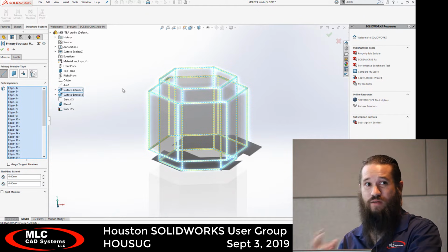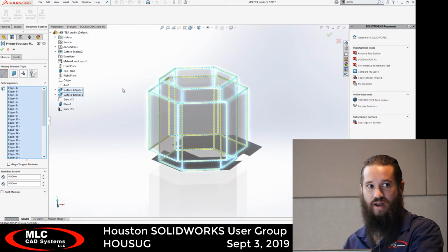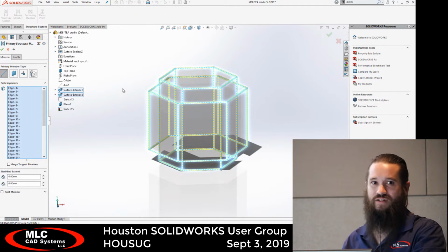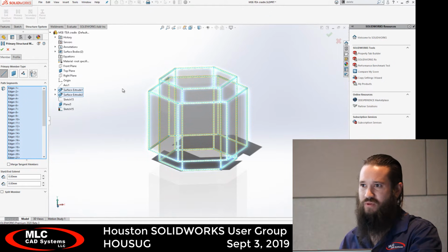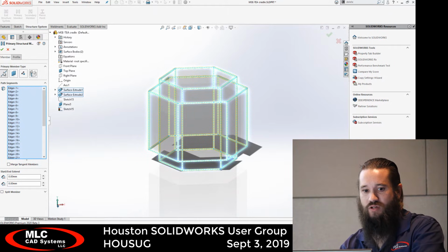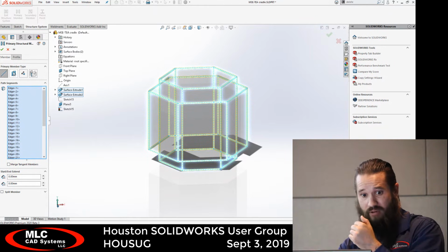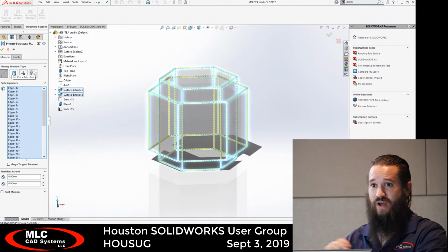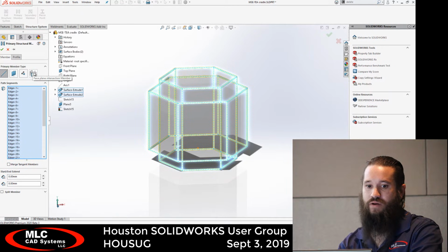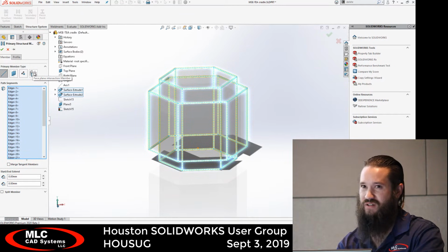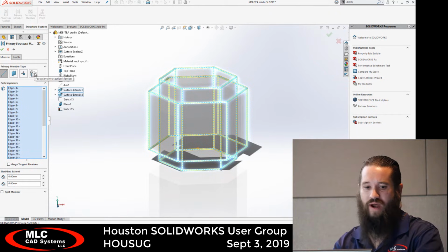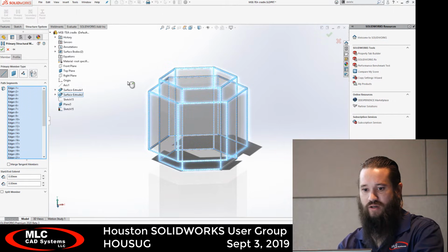Again, these actually use the same profiles that Weldments do, so it's not extra geometries that you have to create. It uses the same data to create it, and it works kind of the same. We just put where we want the members to be. It's the member definition that is very, very different. So in addition to doing those length members, we can also define it by planes, just specifying lengths along planes, or by points in a length, or by an intersection of a plane and maybe a face. And this one is really only used for trying to create curved geometry, so I'll come back to that one in a minute as well. I'll go ahead and confirm this one.